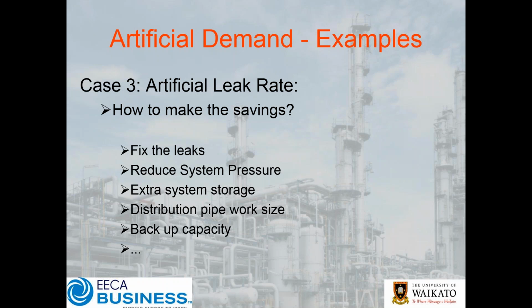To do that, we might need extra storage. We need to look at perhaps our distribution pipe work. Is it the right size? Have we connected up a ring main, or is it just a one-way distribution line? Have you got the right backup capacity in place? Okay, and all in all, it's about looking at how I manage my system and how I manage my insurance.